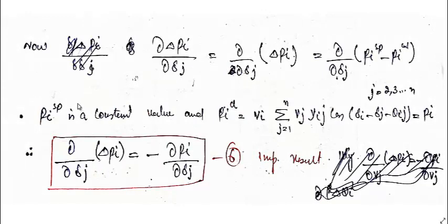So I can write it in this form. First I have to simplify a bit more, because first we'll calculate ∂ΔPi/∂δg, where g can run from 2 to n. I have just written g to differentiate it from i. So this will be equal to ∂ΔPi/∂δg. Here ΔPi will be equal to Pi specified minus Pi calculated. We know that Pi specified is a constant value, and Pi calculated is the value from the equation we wrote earlier, where we dropped the word calculated.